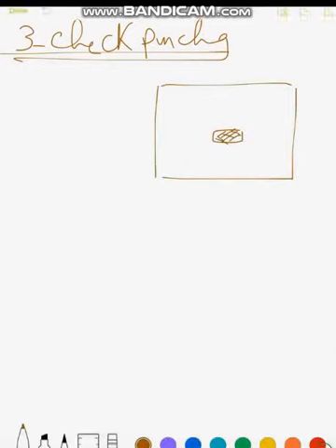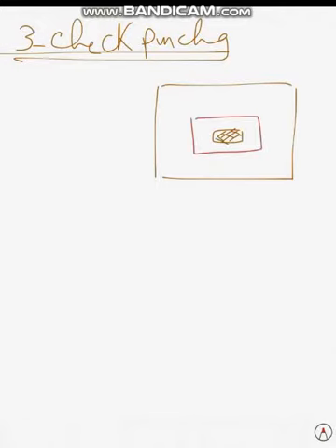Check punching. I need to know that this is a plane of footing and this is a column. There's a critical section around the column where the punching occurs. It is at distance d over 2 from all sides of the column, d over 2. Okay. First of all, I need to determine the Q punch.